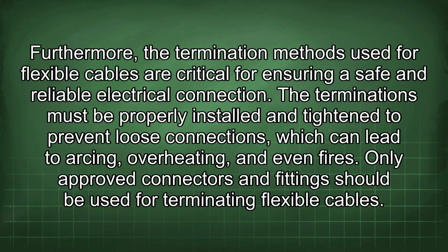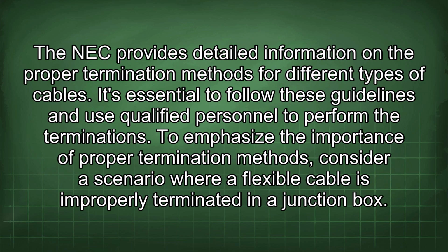Furthermore, the termination methods used for flexible cables are critical for ensuring a safe and reliable electrical connection. The terminations must be properly installed and tightened to prevent loose connections, which can lead to arcing, overheating, and even fires. Only approved connectors and fittings should be used for terminating flexible cables. The NEC provides detailed information on the proper termination methods for different types of cables. It's essential to follow these guidelines and use qualified personnel to perform the terminations.